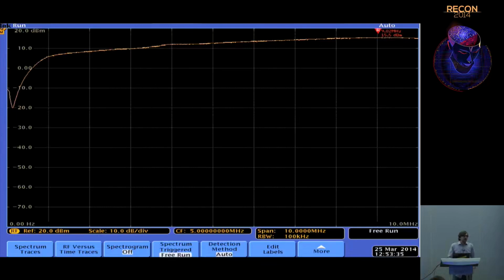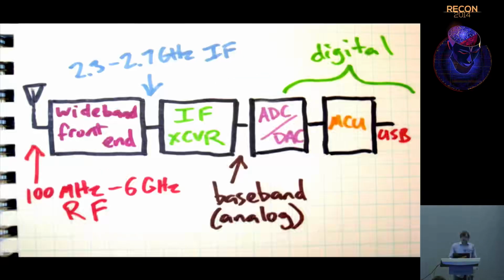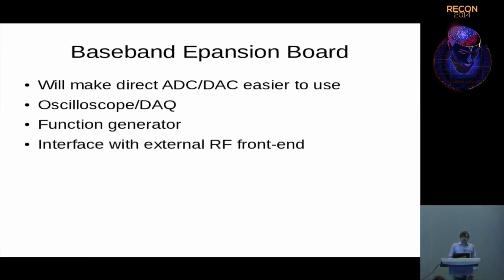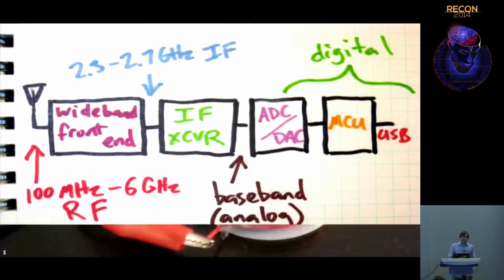A lot of people, when I lowered the operating frequency range from 30 megahertz down to 10 megahertz, said, "Ooh, boy, now that's exciting. We can do high-frequency RFID stuff." But 2 orders of magnitude lower in frequency, down around 125 kilohertz, which is around the little spot where there's the dip at the bottom of this plot, that's where low-frequency RFID operates. And I'm going to skip back to my place in the slides where I should be.